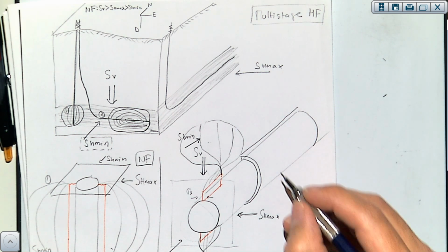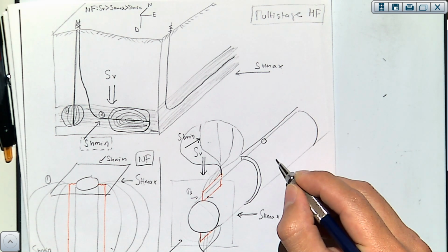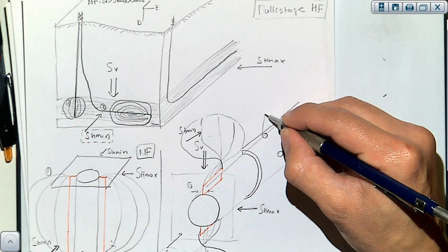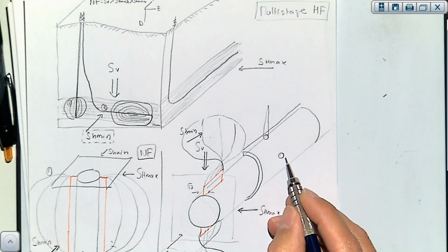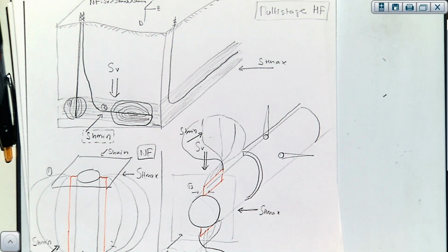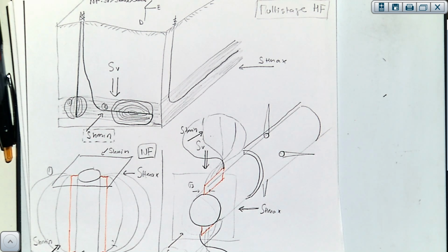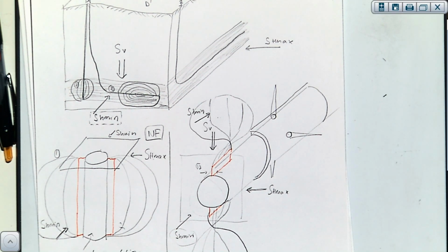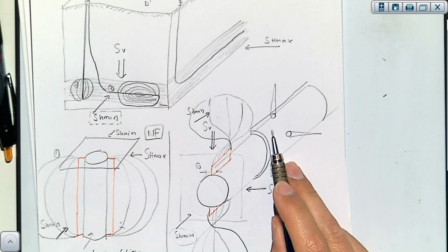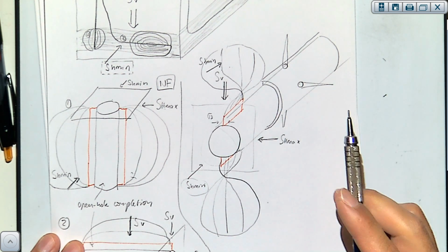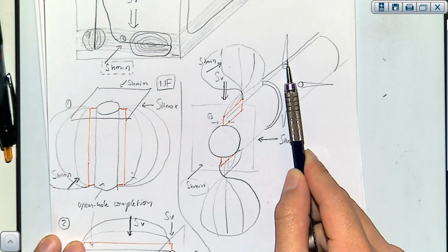And then we make perforations. These perforations are going to be holes into the rock that are going to collect fluid. Now, when you pressurize this casing section and you go through the perforations, notice the orientation of the perforations.